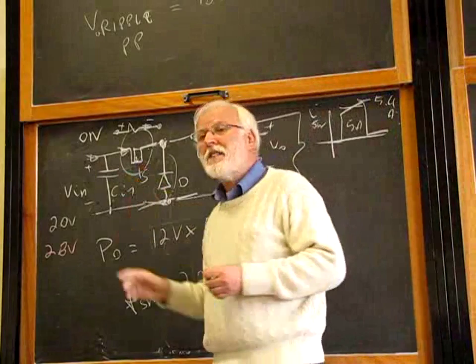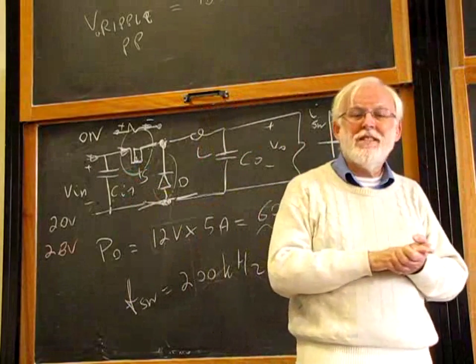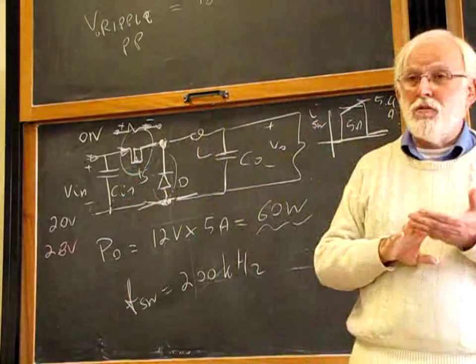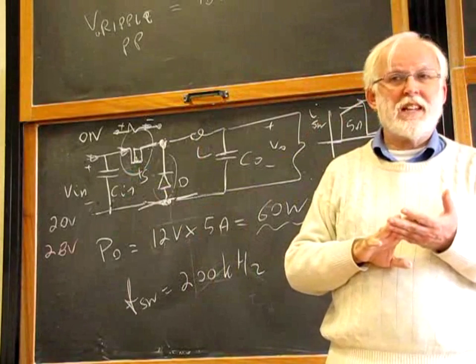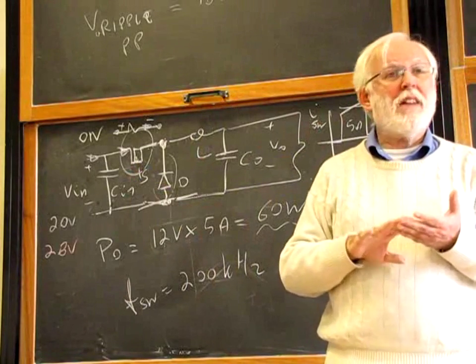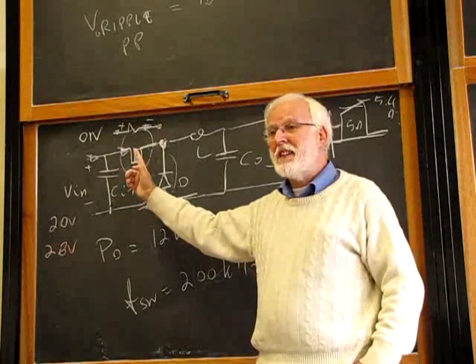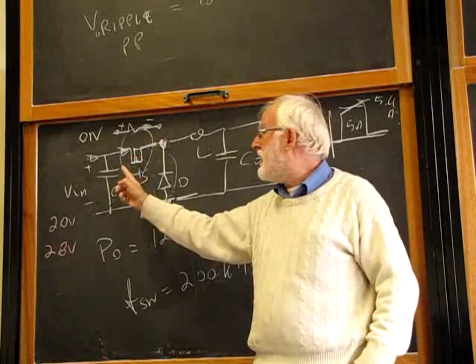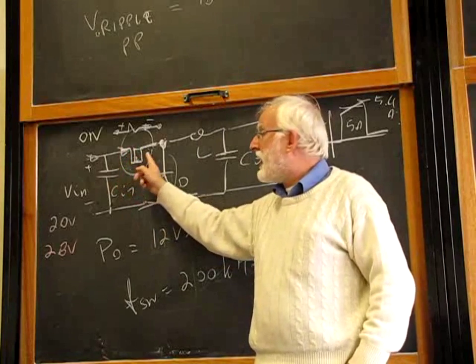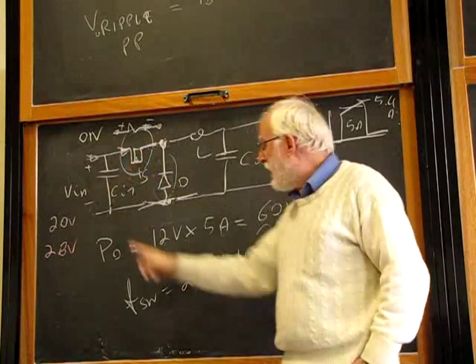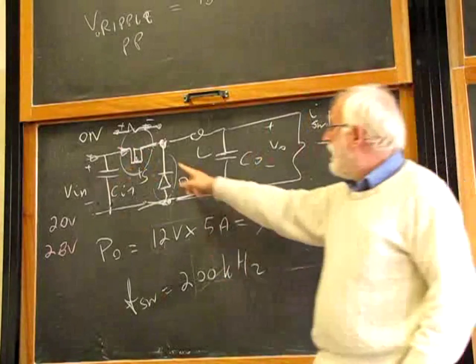Second, a large silicon area is related to parasitic capacitances. And if you have a large capacitance looking into the gate, you have to charge and discharge this large capacitance every time you switch it on and off, 200,000 times per second.